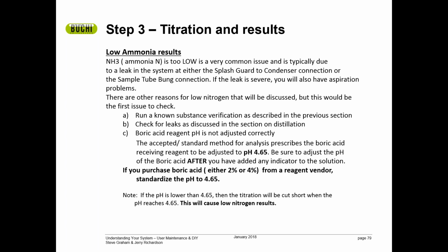Now that we've verified that the system is working perfectly, holy moly, I've got low ammonia. This is a very typical thing to have happen. My ammonia is too low. It's a very typical response. What happens? You have a leak in the system.